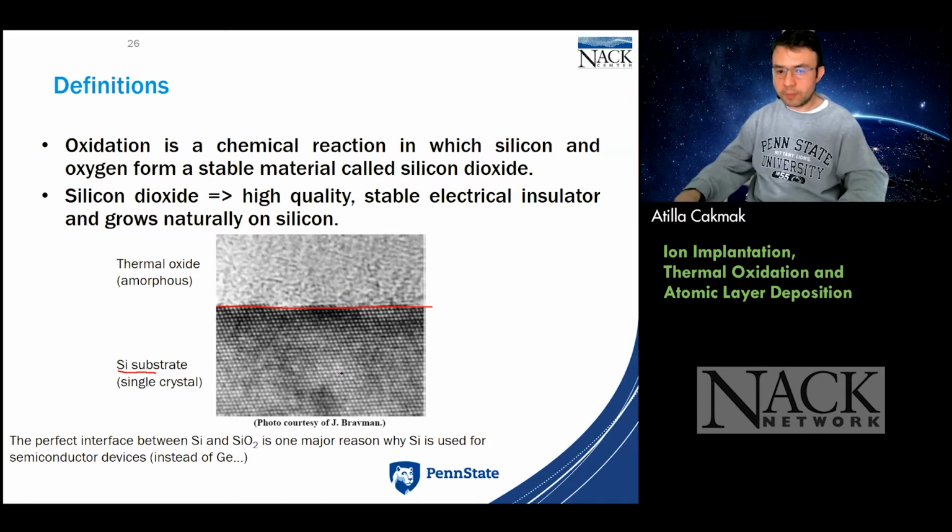How do I know that? Well, silicon can be a crystalline material. So that's why I can clearly see the periodic atoms here located in a certain configuration. Whereas the silicon dioxide, unless it's quartz, is going to be an amorphous material. So there's not really going to be a long-range crystal orientation, a periodic orientation. That's why I don't see that kind of periodicity here. That's good. Now I know which one is which.